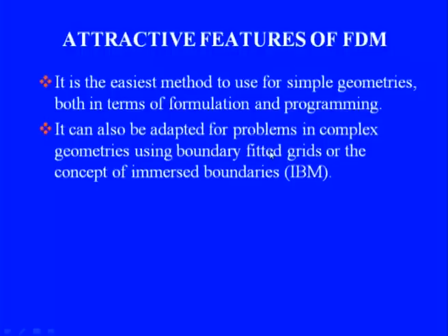In the beginning, to overcome this limitation, people used for complex geometries what we call body fitted grids, but today the recent developments based on the concept of immersed boundaries have left behind the mapping which is required in boundary fitted grids and its limitations altogether, and we can use simple Cartesian grids for modeling any complex application. This point we would elaborate a little later.